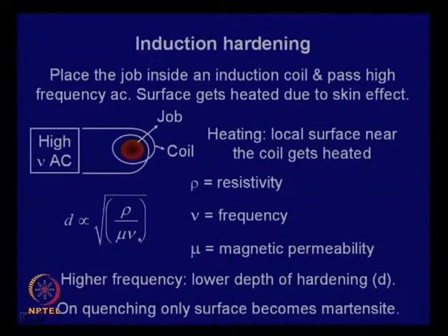And if you use a very high frequency, because of the skin effect, the depth of hardening is low. Depth of hardening can also be increased by increasing the hold time, because if this gets heated, then this heat will get conducted towards the core also. So, if you have a longer heating time, you can control the depth of hardening. By controlling the frequency and the hold time, you can control the depth of hardening.